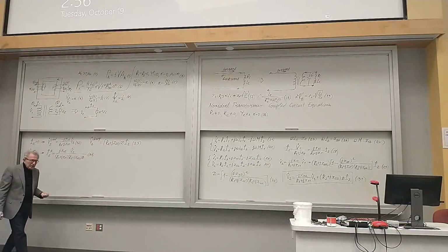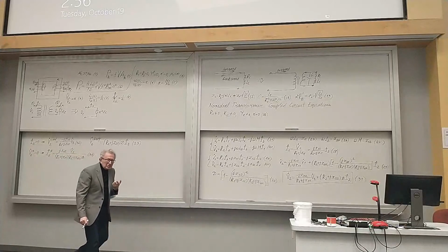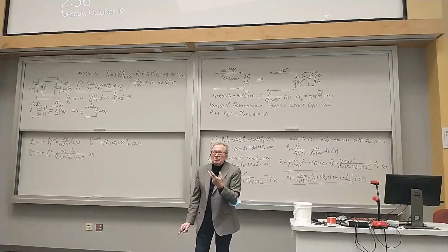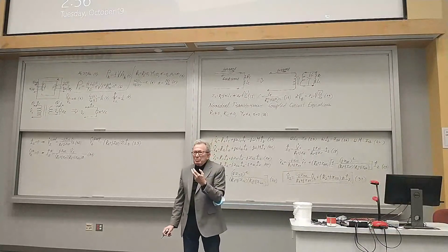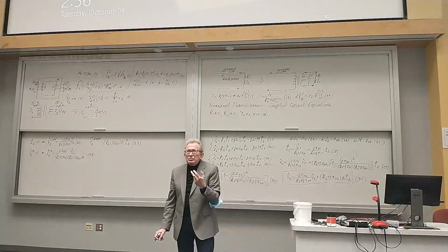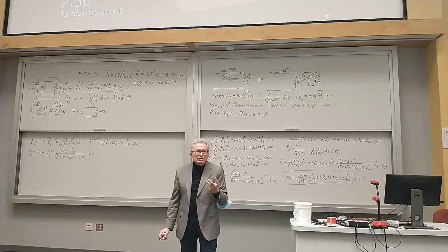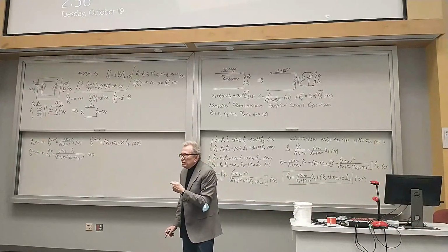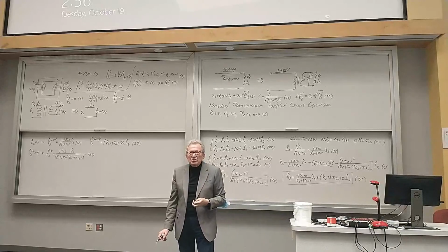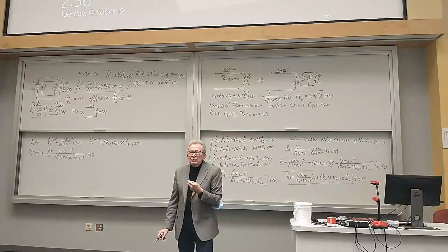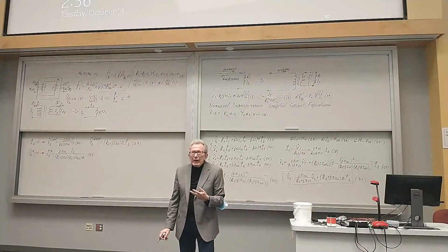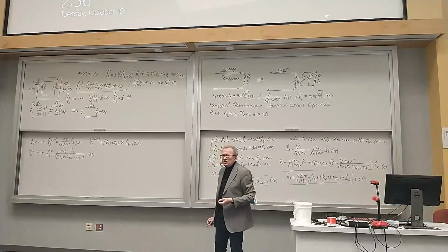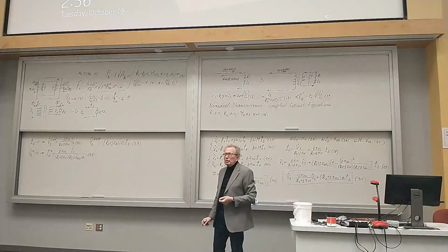But whatever it is, we can see that this parameter d determines the property of the transformer in power engineering. It determines its ability to maintain more or less constant voltage in the face of continuous or predictably changing load, and it determines its sensitivity to the short circuit situation. So this parameter d is very important. And from now what will come? The analysis of all this d. What this d depends on.